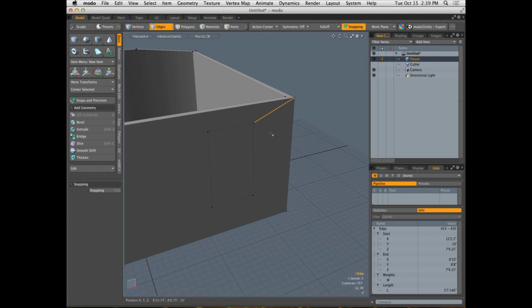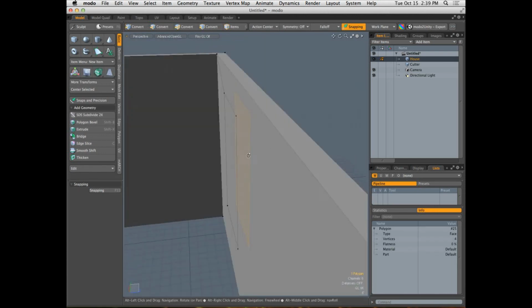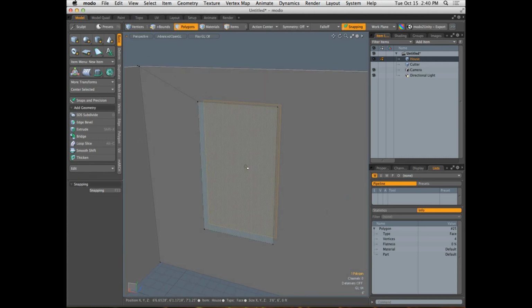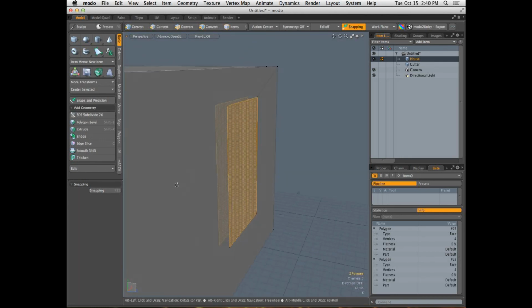Okay? So this is really kind of the benefit of working with these Booleans, is that it's going to allow us to very quickly go in and slice our geometry based on the location, size, and shape of another piece of geometry. Okay? Pretty rad. Check it out. So there's the two pieces, the polygons that I worked with. Now I need to make a window from those two polygons. How do I do it? Got to bridge them. I like it.